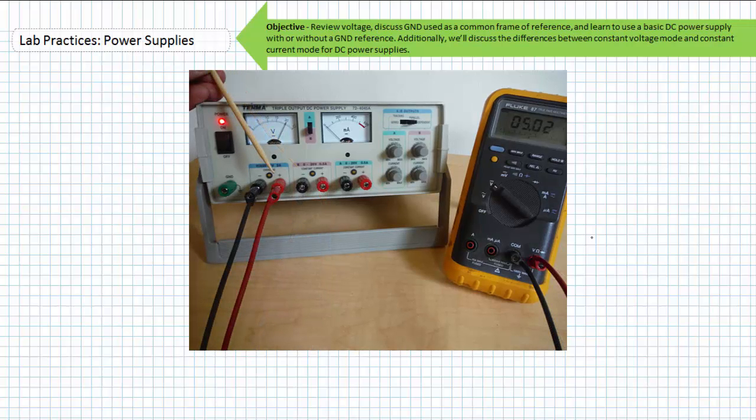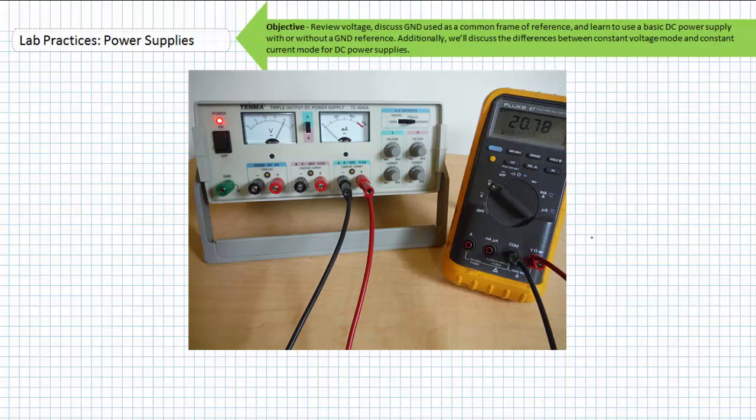While we're at it, let's check out the third terminal set. We're observing 5.02 volts, regardless of the position of the knobs, because this is the fixed 5-volt supply. Let's get our A voltage knob close to 20 volts using just the needle meter and check it using the DMM in voltmeter mode. It shows 20.78 volts. Not bad, but we could be closer.